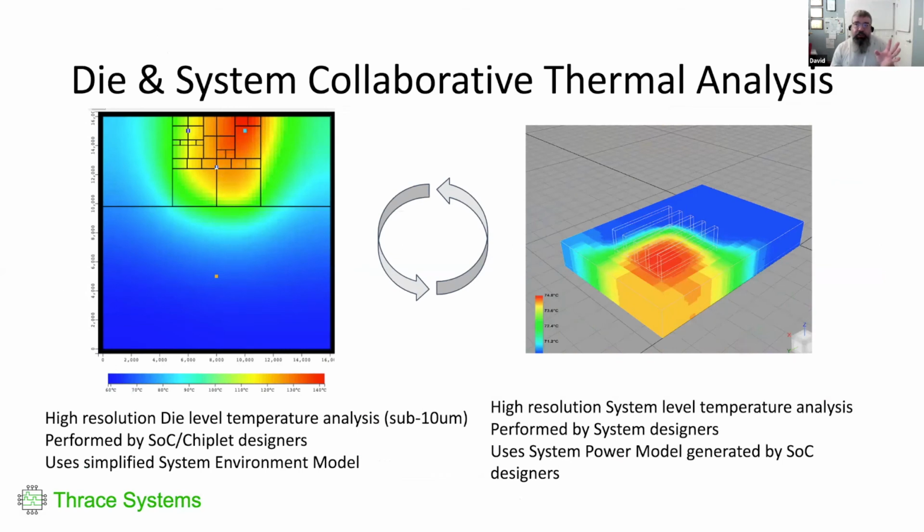Now, taking this a little bit to why we're here is to talk about thermals. And thermals are a very interesting topic. They depend on power a lot. Thermal simulations would be done for different purposes, depending on which way you are looking at the system. If you look at it from a chip level point of view, you can live with a slightly coarser view of what the system looks like, some simplified view. But what you're targeting on that level is to understand where your hotspots are, where to place the temp sensor, and make sure the temp sensor is placed where the hotspot is. Otherwise, you're not measuring anything.